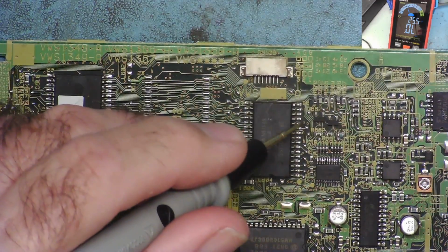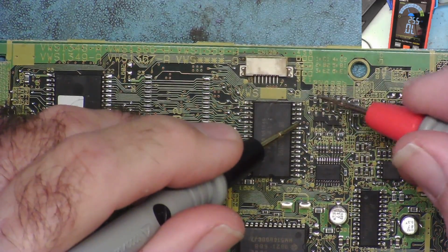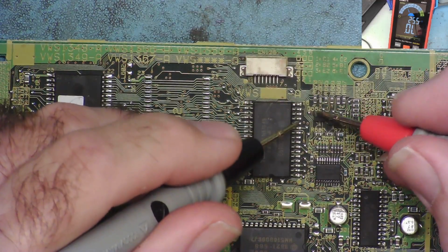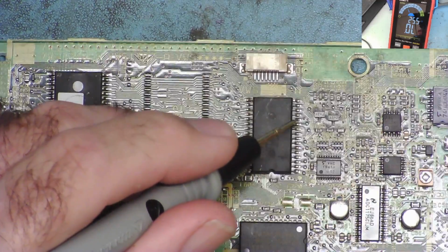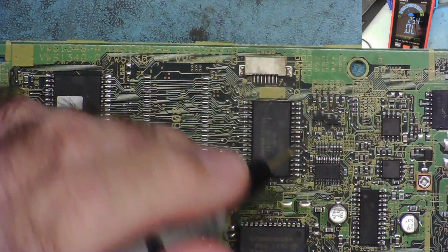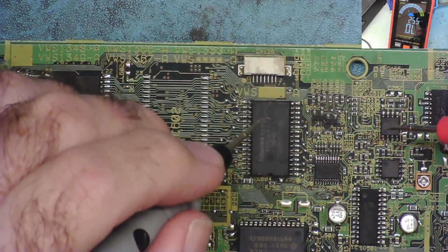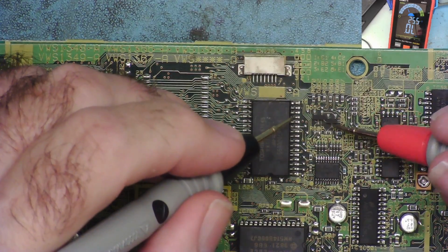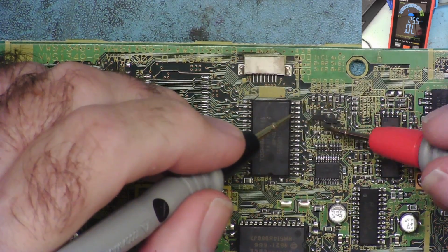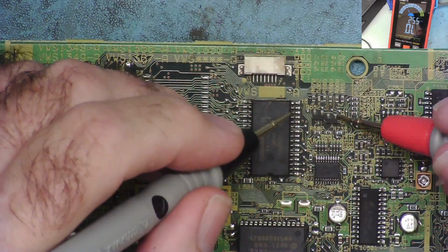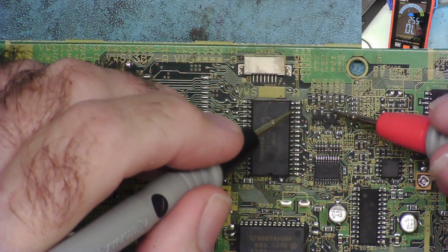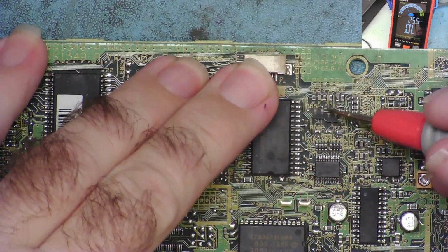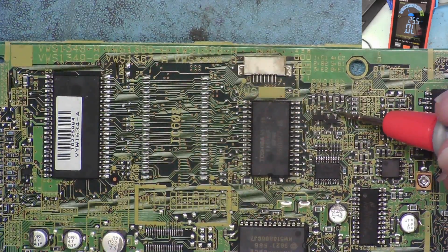The best indication that they're going to be transistors of some sort is that the part number is Q. Not the part number, but the identification number. Q662, Q661. Yeah. So let's have a look at these and see if we can see any semiconductor junctions. Normally with these, the pin that's on its own is the collector. And usually this is the base and this is the emitter. But I'd say usually. I mean, these look like these 2 pins are actually connected to each other, which is not uncommon to find.